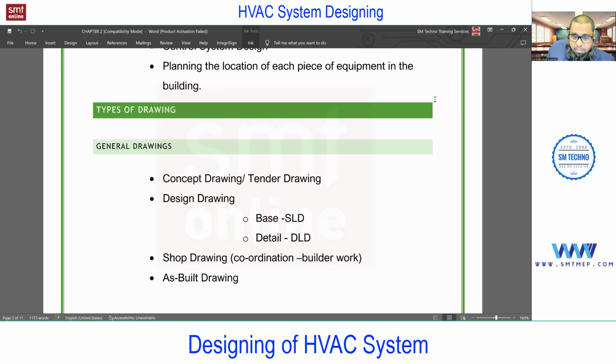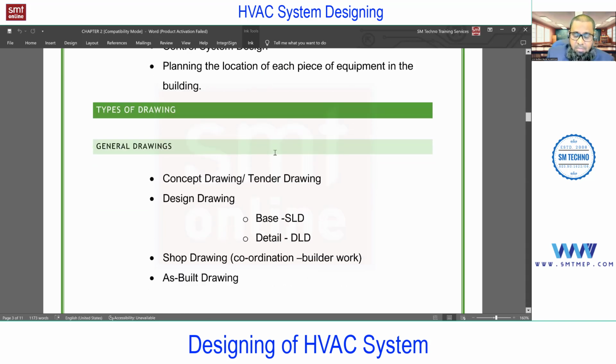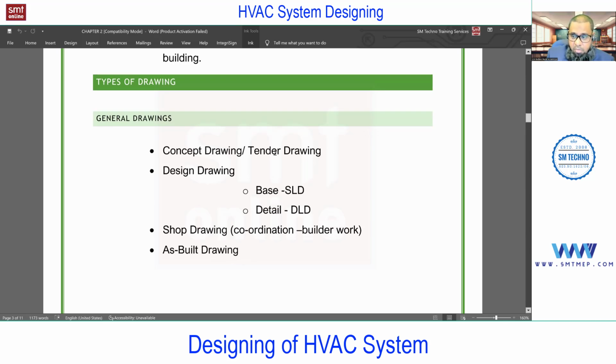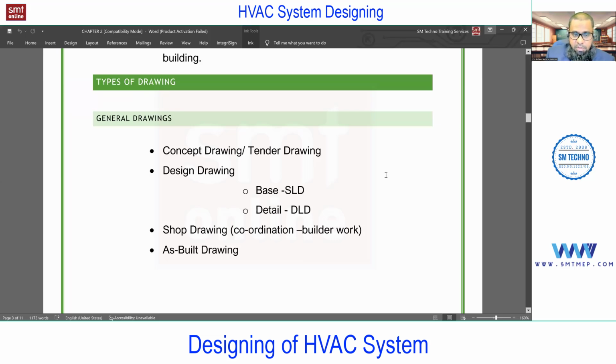See, which bear the load of the building, including mechanical and electrical equipment. So that's the reason the structure will again be updated after completing the mechanical and electrical services, based on the load of the equipment. For example, in a project, if you want to place an air cooled chiller, which is big in size, I'll show you the image of a chiller at the time of chapter 5. Assume it's a big piece of equipment, if you're not aware of this, with a load of say 1000 or 2000 or more kgs, that means it is going to be in tons. So if you want to place this heavy equipment on the roof, the structure must be designed accordingly. According to that, the structure people will take care to bear the load.